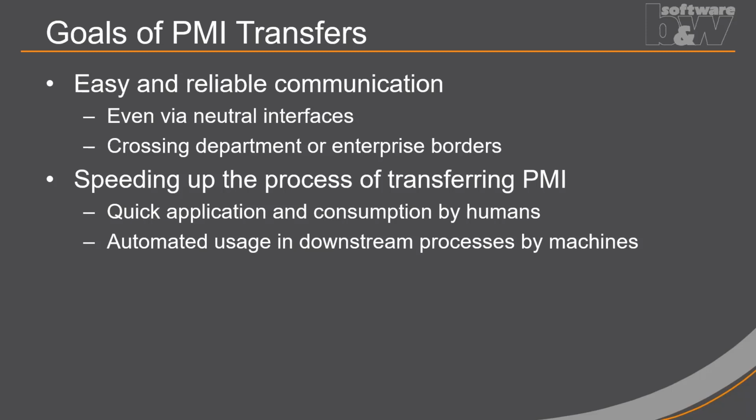How should the PMI transfer be? We wish it to be easy and reliable for downstream communication, even via neutral interfaces like STEP and JT and so on, within the company and across the borders of the company. We want to speed up the process of transferring PMI, and a main goal is to reduce the amount of work for the designer, because when doing MBD, the downstream processes will profit from it most. The design area will have more effort to create the content, or just have a new process to apply. Therefore, it should be easy and effective to apply the PMI in 3D.